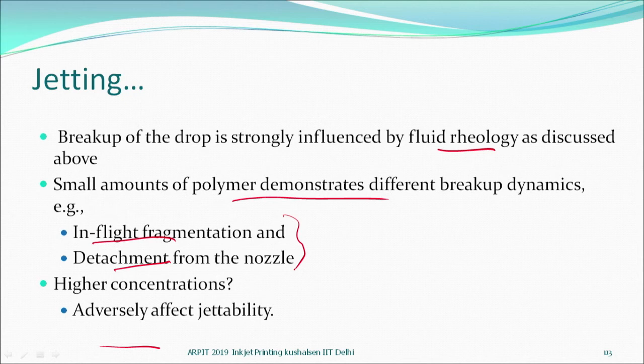But if you have higher concentration, then it will adversely affect also. So, you can't just add. The jettability is going to be adversely affected if more polymer is there and viscosity is increased too much. Pressures also will be high, electronics may also not be able to sustain.